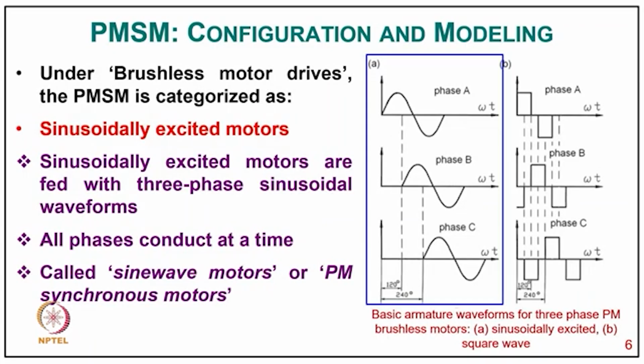Now, coming to brushless motor drive, the PMSM is categorized as a sinusoidally excited motor, as you can see in the diagram. Sinusoidally excited motors are fed with three-phase sinusoidal waveform with all-phase conductors at a time and are called sine wave motors or PM synchronous motors.